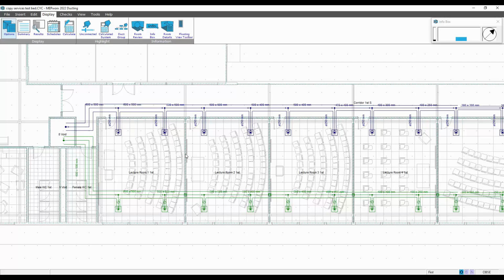There are checks and balances in place to make sure that the services you are copying upstairs are sized correctly. So if you imagine you're looking at the heating as your basis of your calculations on the ground floor and you have a ground floor exposed floor plate, if you're copying that upstairs, obviously there's going to be a modicum of oversizing because the losses upstairs will be slightly less because you only have an external wall. So there are checks and balances in place.